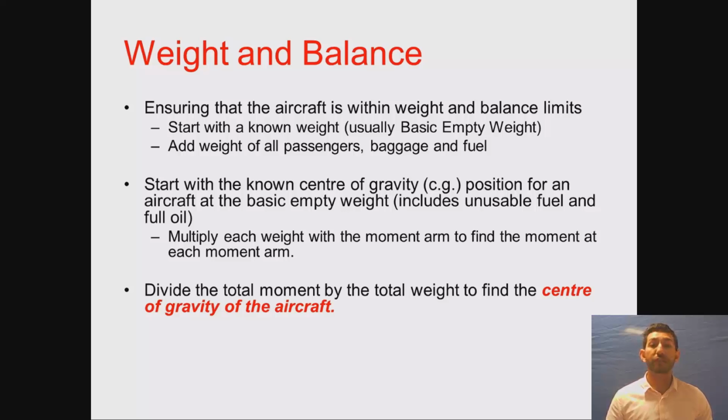Fairly easy, fairly straightforward. With getting the moments, you take the center of gravity of the aircraft at that basic empty weight, and multiply that weight by that moment arm, the distance from the datum. As long as you use the same reference datum for all of it, then you're okay. And then if you divide the total moment by the total weight, you can find the center of gravity of the aircraft.